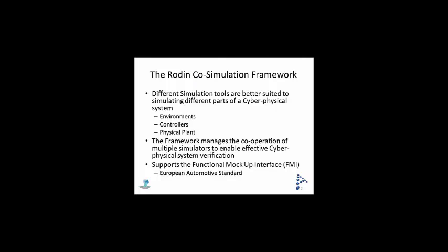So the co-simulation framework, and this is really why I've been talking about cyber-physical systems, is that there's no way that a single tool vendor is going to be able to provide a simulation environment that will work with all the different environments that are needed for these cyber-physical systems. So what this co-simulation environment allows you to do is to model the environment in MATLAB or Modelica and then link it with your discrete model. And then you can also take, if you have a hardware block which is discrete logic, you can simulate that as well. So you can have multiple simulators cooperating.